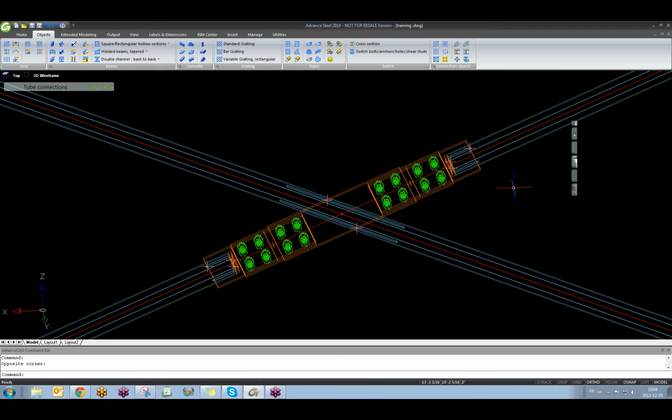So you can go to your objects. You don't even have to select angle bracing again because it defaults to whatever your last one is, if you're using the same material. So just zoom in on that area and find that intersection right there. And zoom out. Same thing down there. You can adjust your positioning after you have your bracing in. And so now what you can do is deselect that. Just hit escape.